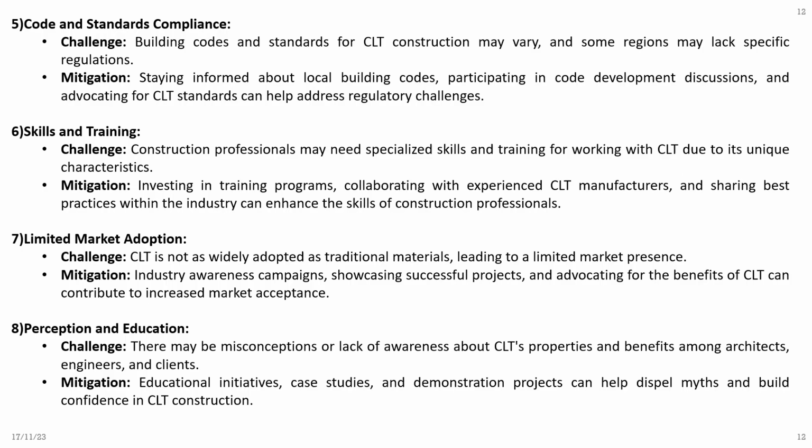Fifth, code and standards compliance challenge. Building codes and standards for CLT construction may vary, and some regions may lack specific regulations. Mitigation: staying informed about local building codes, participating in code development discussions, and advocating for CLT standards can help address regulatory challenges.